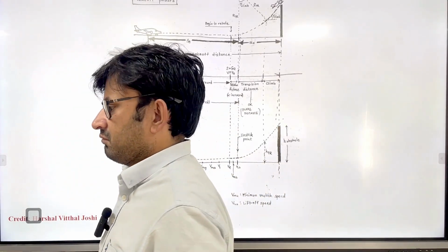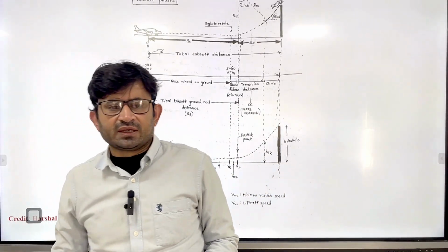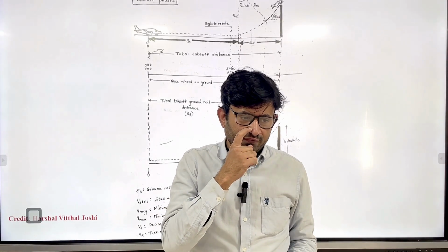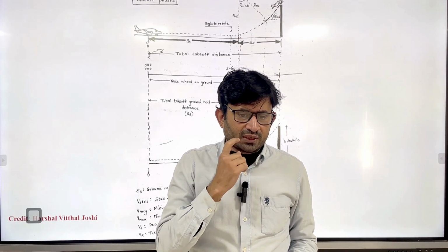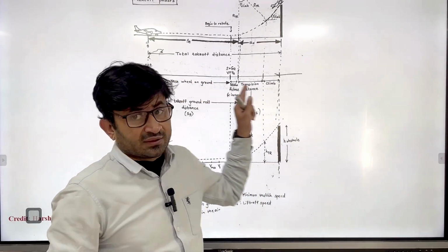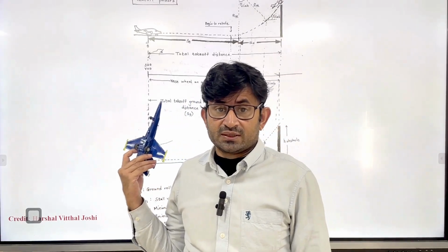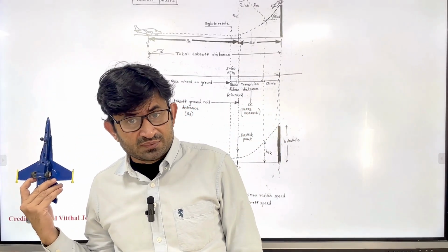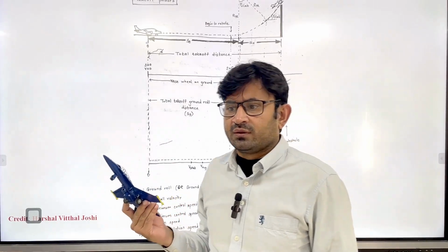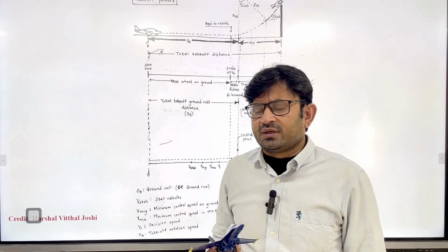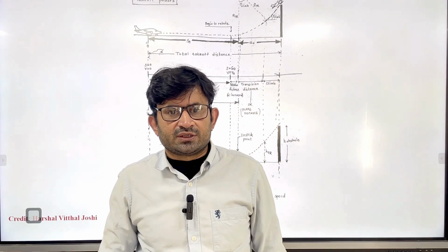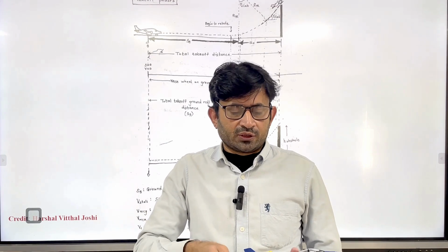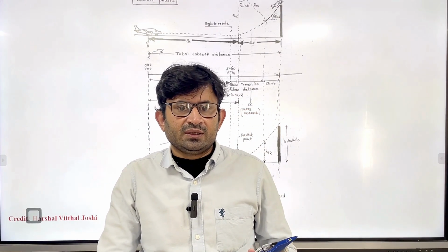First, how does the pilot perform the takeoff? You can have a feel for it. When you are about to take off, you will put on the throttle and monitor the speed, like I said: Vs, V1, VMC, every speed you have to monitor. Once you reach that speed, perform the action accordingly. When you reach the rotation speed, you have to put the elevator up in order to rotate the aircraft.